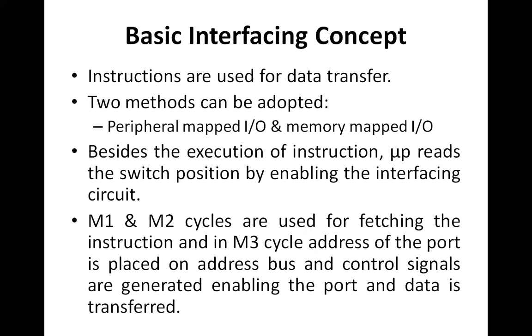Both these instructions, the IN instruction and the OUT instruction, have a certain format of use. Both these instructions are 2-byte instructions. One byte is meant for the IN operation or the OUT operation, and the second byte is meant for the 8-bit port address. So you can say that both these instructions are 2-byte instructions having their hexadecimal codes, and the second byte will be defined by the port address of the input device or the output device.